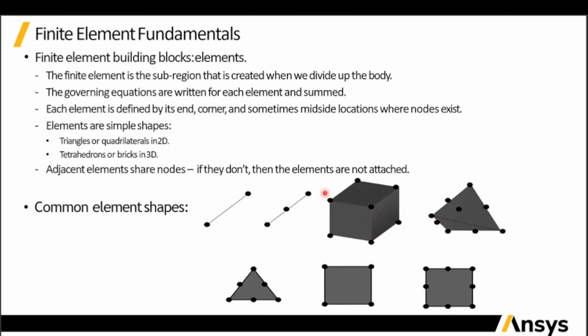So when will you use one-dimensional elements? See, there is nothing like a 1D thing that exists in nature, right? But for our simplification, we consider a few structures as one-dimensional structures, like we solve a few problems in our strength of materials, like a beam element, or column elements, or you work on shafts. For the time being you consider those as one-dimensional elements.